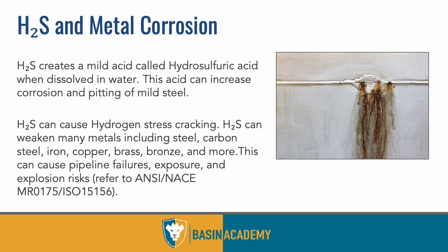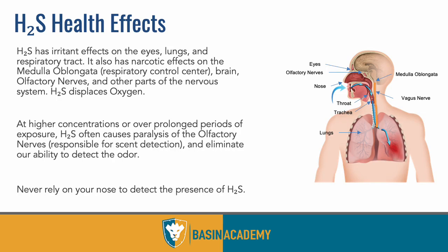Improper treatment, if we're putting water down hole where organic material will break down and then release sulfur, and then the hydrogen that's in the water and oil and the sulfur from the organic material that's breaking down will bond and create H₂S. So untreated waters, a lot of different things can turn a non-sour well into a sour well.